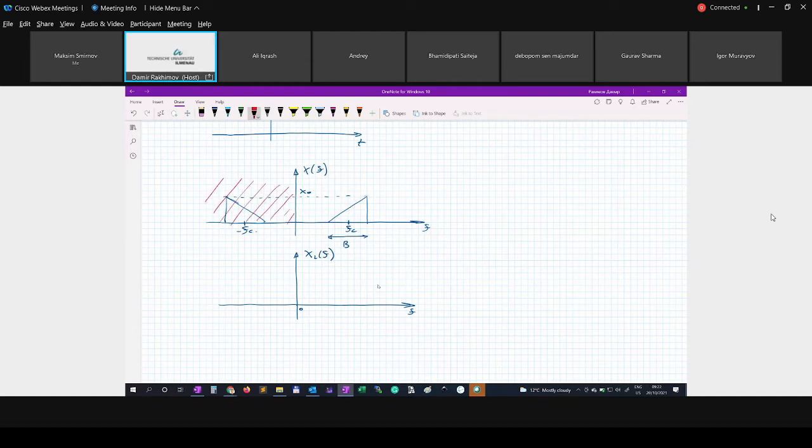Second step, the remaining part in the positive range of frequencies we move by the frequency with respect to which we perform the transformation. As a result, we get a signal at the origin that goes from minus b over 2 to b over 2. And what's the amplitude? The original amplitude was X0, but as we mentioned, it's not the end. We have to do some changes. What will be the final amplitude?